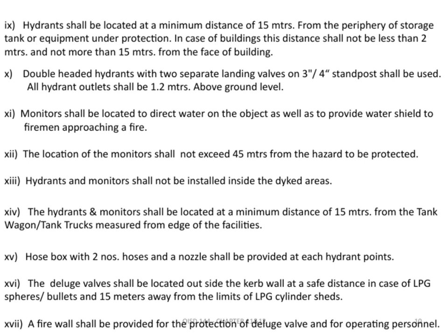Monitors are essential as well. They should be placed so they can direct water onto the fire object and provide a water shield for firemen approaching the fire. The placement of monitors should not exceed 45 meters from the hazard, ensuring effective water coverage. It's also important to note that hydrants and monitors should not be installed inside diked areas to prevent potential safety